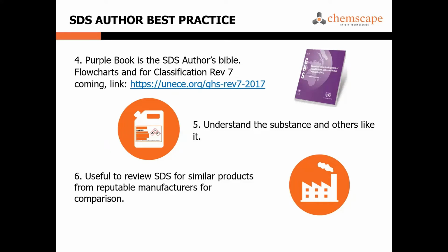It's useful to review the SDS for similar products from reputable manufacturers. So when being an SDS author in the oil and gas, yeah, I'd line them up, BP, Exxon, all these. And that's a funny story. Just before the Lac-Mégantic explosion, a couple of years before that, I had written an SDS for sales oil coming out of our Saskatchewan Bakken, and I called it Bakken crude. I had all the data, and I got some backlash from the big guys. I got emails after they found my SDS, and I had made it a packing group 1, highest flammability from a TDG standpoint, and a GHS.